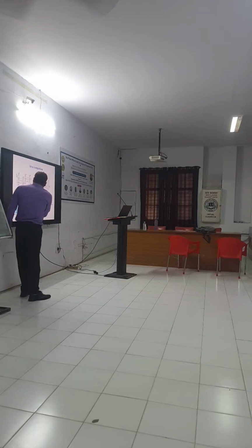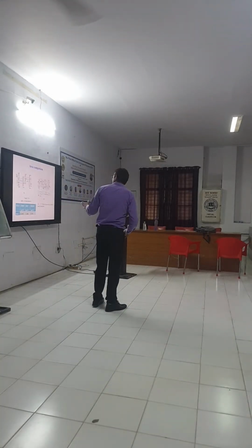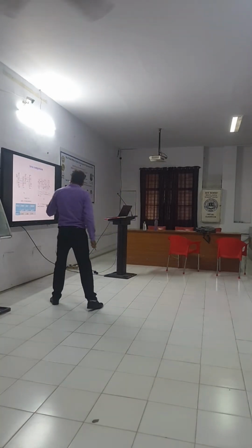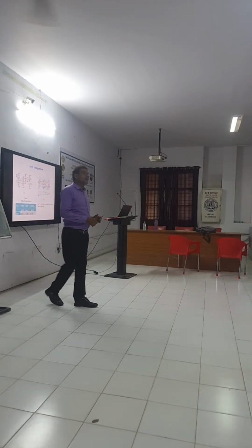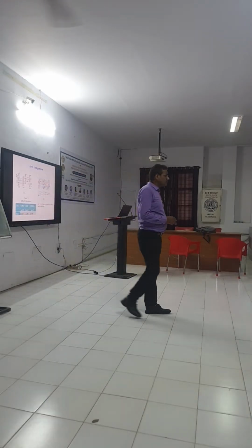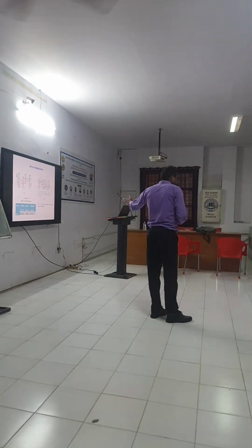So see, this conventional one's area is 0.518 micrometer. It is 1.0. It is 0.77. You can think, sir, why do we have more? See, this zigzag 80 is 1.0 micrometer. We are getting 0.7. So as compared to this, our area is also less. Sir, how are you getting less area? That's also possible, because with the same number of MOSFETs, you can get less area.